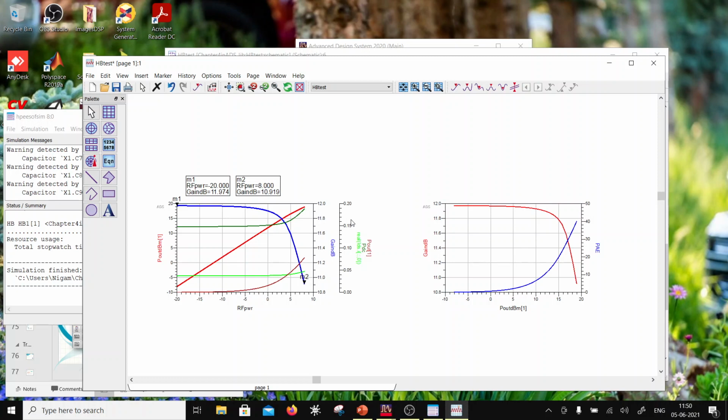In a BJT you can put the input power for driving the device, right? And so you are causing a voltage swing on the input as well as a current swing, and both are being amplified. The current swing is amplified by beta, while the voltage swing is basically gm times RO, times the input voltage. That will be giving you the gain.